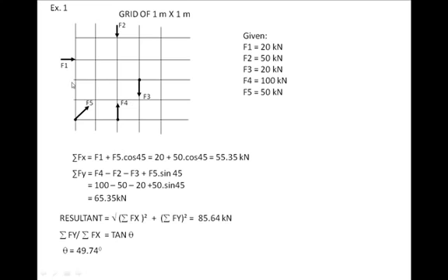But while you transfer, as you are aware from the first video of this series, any transfer of force creates a moment, and it is necessary for us to keep track of these moments. So this equation, the last equation which has come, does that. Let's say the first term. What is this? It is 20 into 3. It is F1 transferred here, so it gives a moment of 20 into this perpendicular distance 3, and the sense is clockwise, and with our convention we have taken clockwise as negative, so this is negative. Similarly, we have done this for every force.